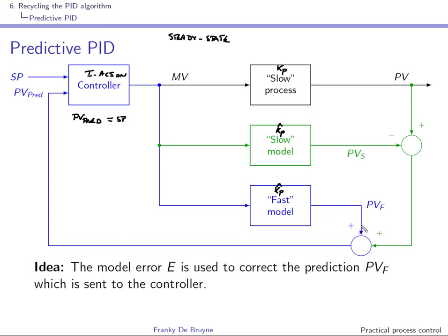So as you can see here, you will have the influence, and here we can again assume that we have a disturbance that is constant, right? So here we'll have Kp, Mv and d, right? And here we'll have minus Kp hat Mv, right, coming from here, and here we'll have plus Kp hat Mv.